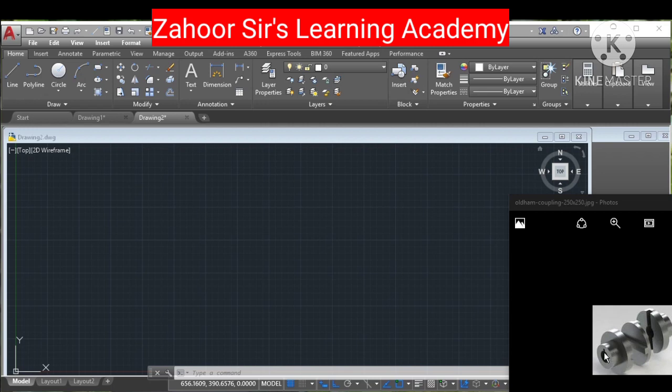Apart from that, it also has a slot. The slot is for the key, and the key which we are using is the square key in this case. These flanges are individually fixed on the shafts which are misaligned, and this disc connects the two shafts. So this is the theoretical background of the coupling, and now we need to draw this coupling.